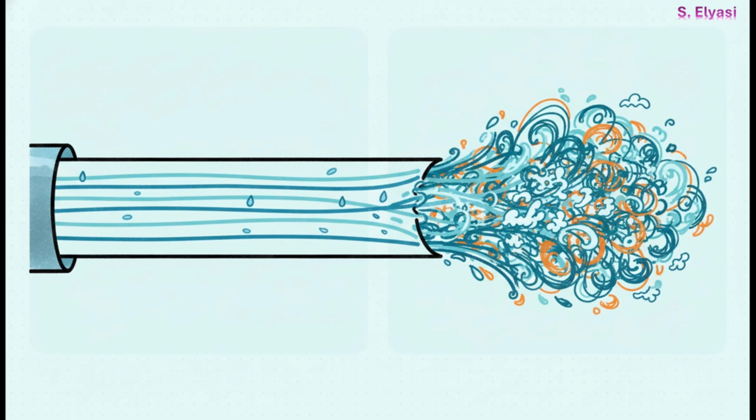And this right here, this just nails the difference. When the Reynolds number is low, viscosity is winning that tug of war. You get that smooth, predictable laminar flow. Think of a lazy, slow-moving river. But when the Reynolds number is high, inertia takes over and you get chaotic, well-mixed turbulent flow. We're talking whitewater rapids. And the Dittus-Boelter equation, it's made for the rapids.